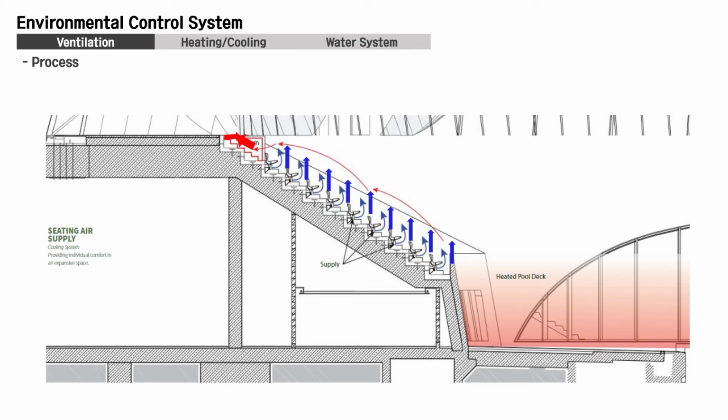As the air gradually rises in temperature, it also begins to rise physically and is collected in the larger return vents located at the top of the stands. Low-velocity jets at the top of the stands also shoot heated air into the expansive cavity above the pools, which helps prevent any unwanted draft in the comfort zone.